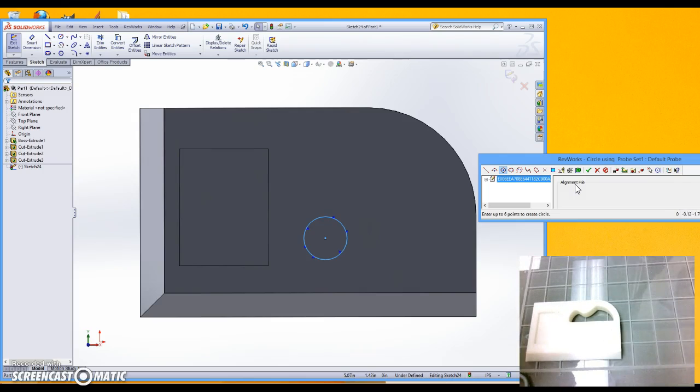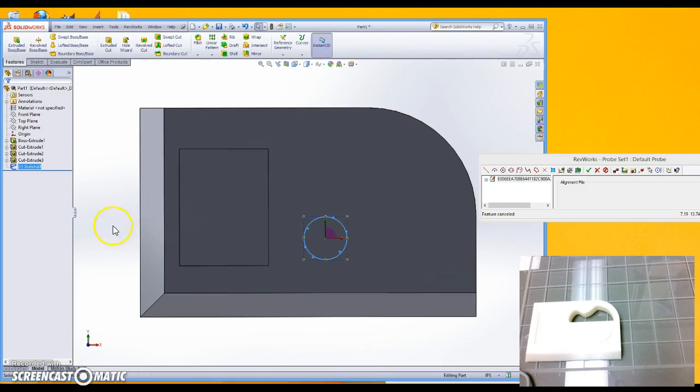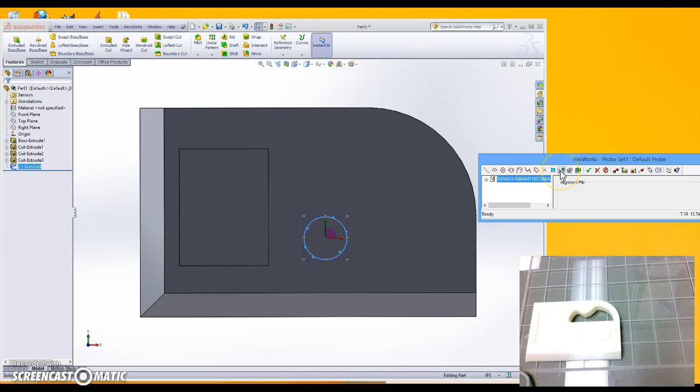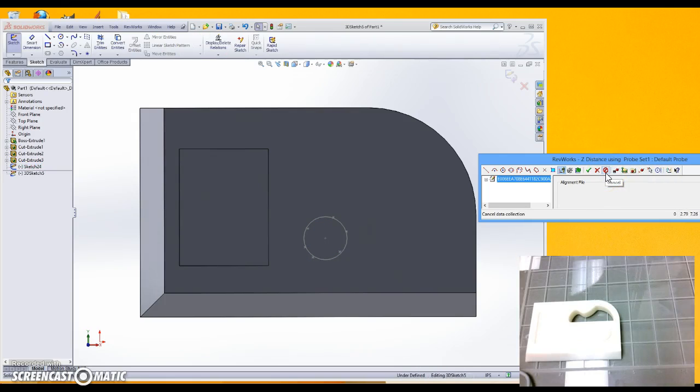And I can go ahead and do the second circle right away as well. We'll actually do the first circle first because then we need to extrude them a little bit differently. So I can exit my sketch. We'll make a measurement again of how high we want to go. In this case, it'll be a delta Z value again. And that will be from the base to just that very top edge before it goes down inside. And 0.14 inches is our extruded height.